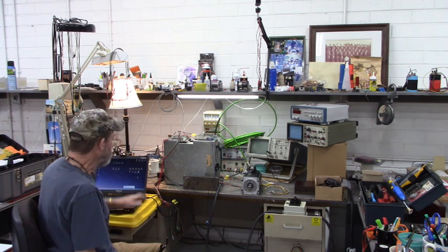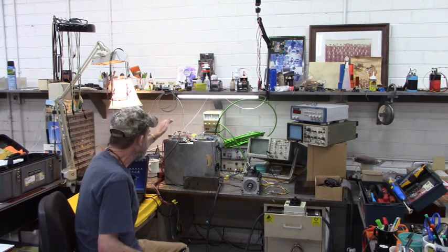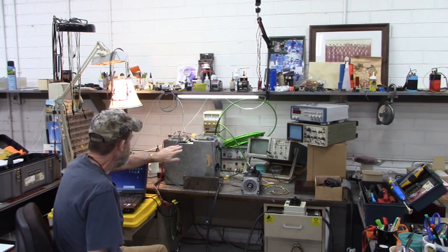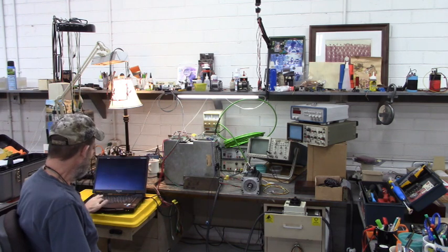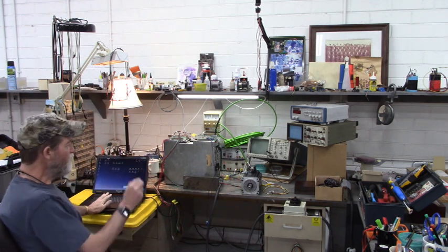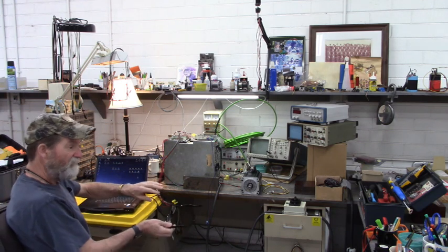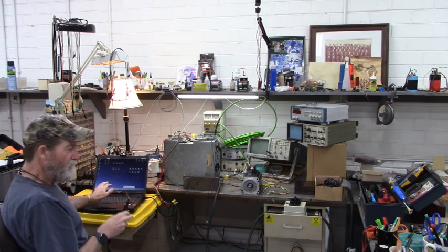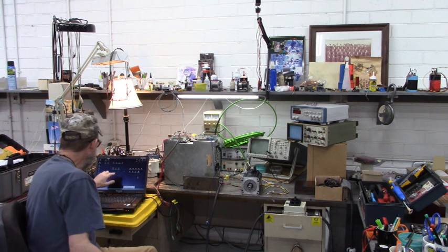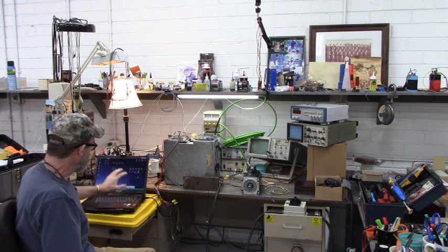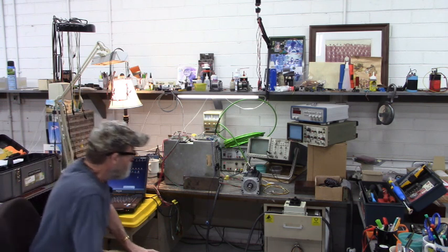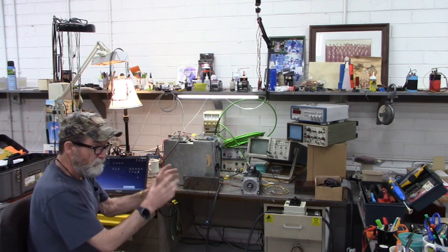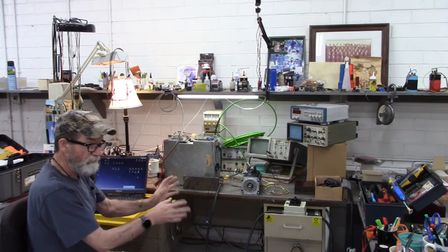So here's our bus power supply and Indramat servo drive. And I have communications from the servo drive to the laptop here. When you power up that servo drive, it actually emits data from the servo drive to the laptop, and we're going to use HyperTerminal to view that data. Let's go ahead and power up the system and make sure we have a good encoder and good motor before we do anything.